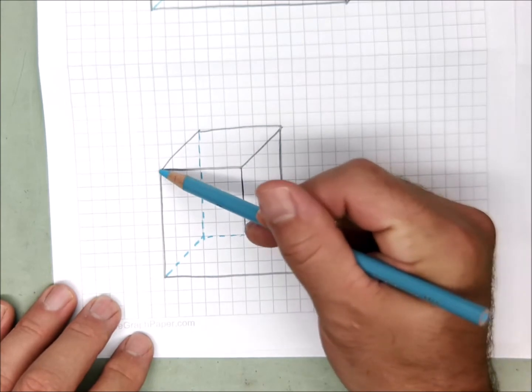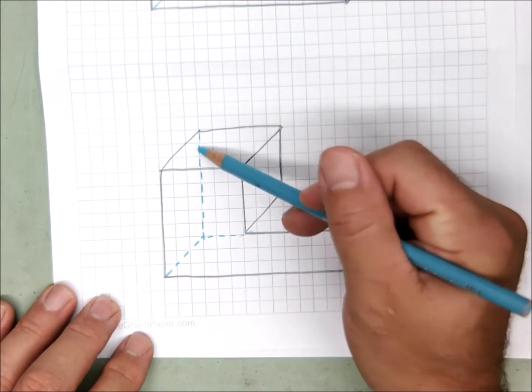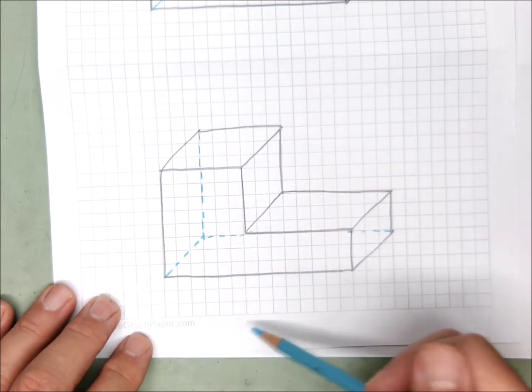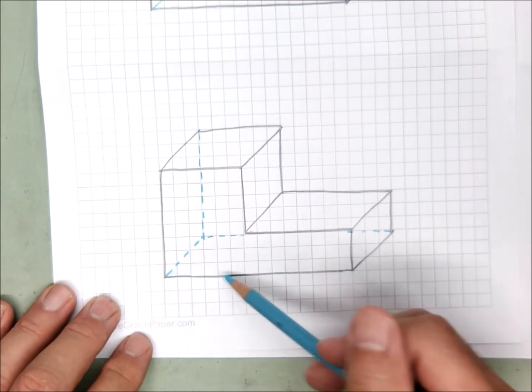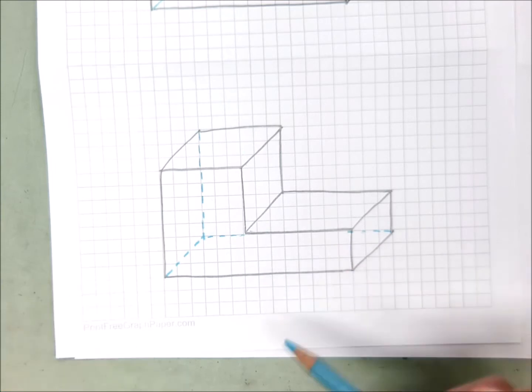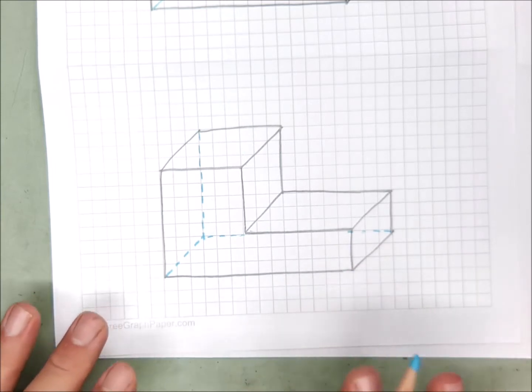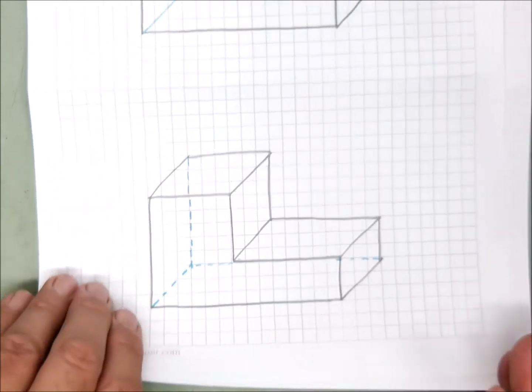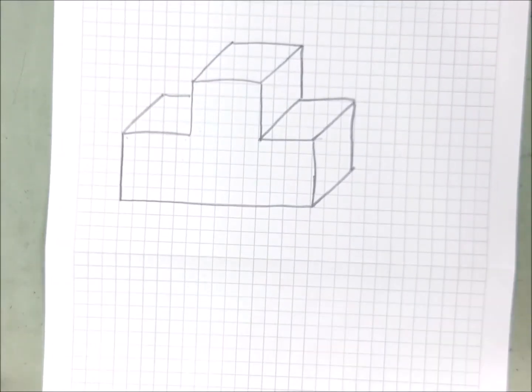By bringing that corner down to here, it means in the back the same thing happened. By bringing this corner down to the left horizontally, well, we know back here there's a corner also along that back face. So please don't add hidden lines to your oblique drawings, but understand that there is stuff that we don't normally see.